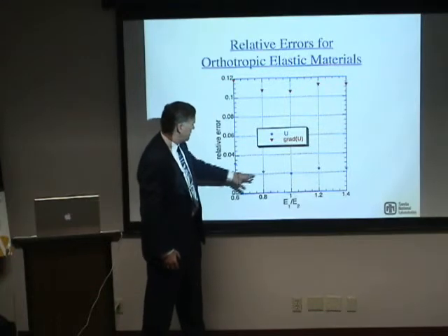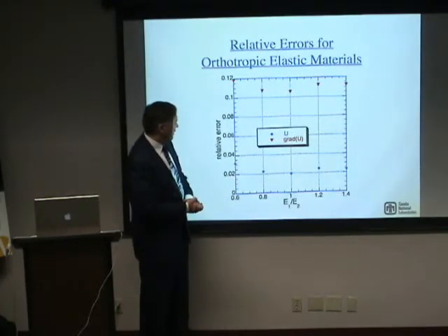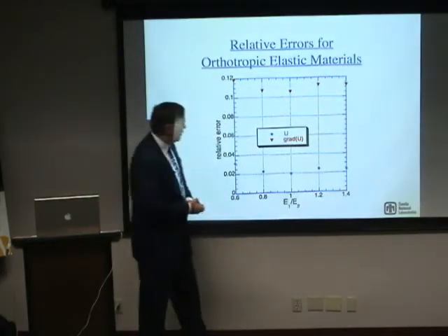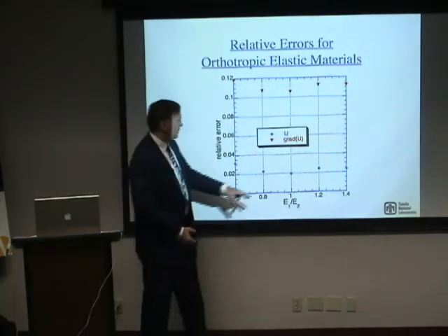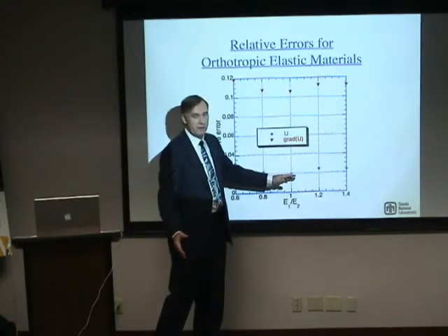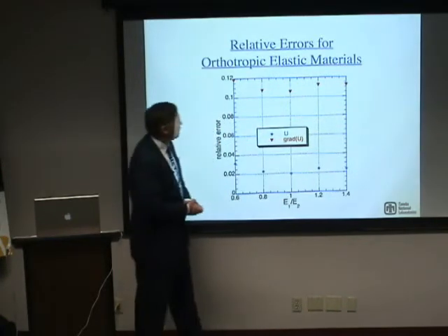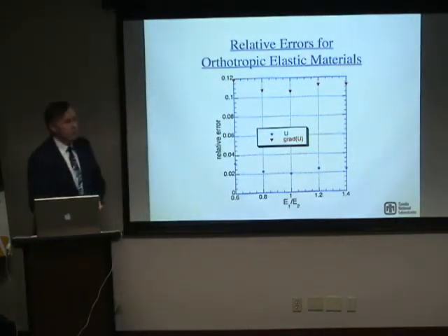You can see as we change to 80% and 60% for E1 versus E2, and then going the other direction, that our error does increase. So one of the positive things here is that we're really happy that the isotropic solution was the best one, since that's what the analytical solution corresponds to. But you see an increase in it, but I would say it doesn't increase so quickly that we would be hesitant to use it for all problems that include anisotropy.